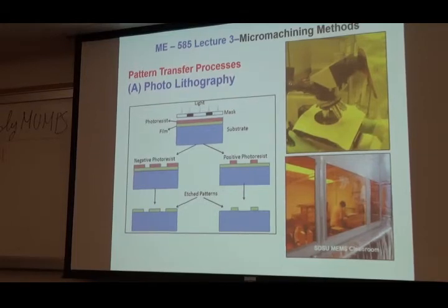Yes? You explained about photoresist. Does negative photoresist harden when exposed to UV? Yes, it's the opposite. Very good. In fact, I was going to forget mentioning that now. Positive photoresist, the key word is this part which is transparent, the polymer actually gets depolymerized, which means the crosslinks are broken.